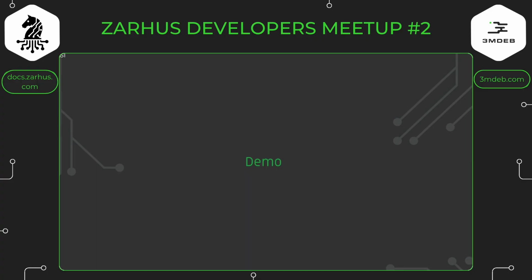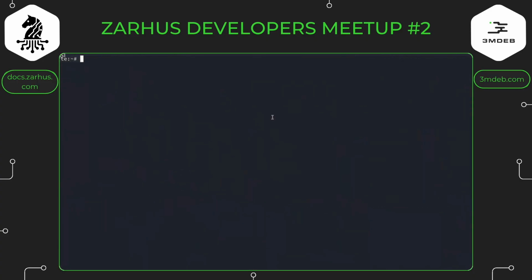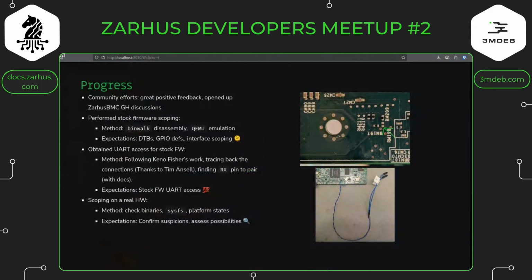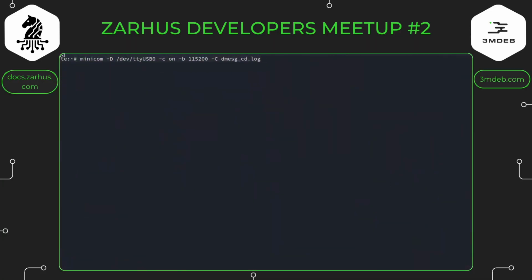Yeah, and I prepared a little demo. It's not much, but I think I can show you that we indeed have access to the stock BMC firmware. Right now we are on RTE, the platform that Piotr was talking about, and we will use Minicom to connect to the UART adapter that's connected to the X11SSH platform. If you can go back a bit, you can see in the picture at the bottom how I hardwired into the platform, and this is basically how we got the connection. Let's go back to the console, and we are already at the prompt.